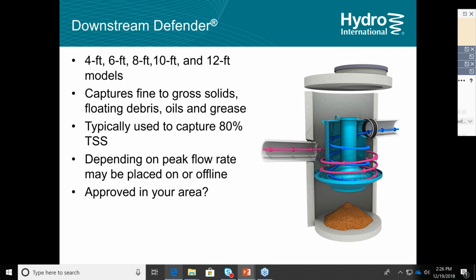If you wanted to pass 17 CFS during the 100-year storm and you had enough freeboard in your system, that would be acceptable. It's a very infrequent event. You've got enough freeboard, it's not causing any flooding. We're not concerned about the internals getting damaged. So that's acceptable. So it's another situation where if your design parameters don't meet the product literature, it would be a good idea to reach out and contact tech support.